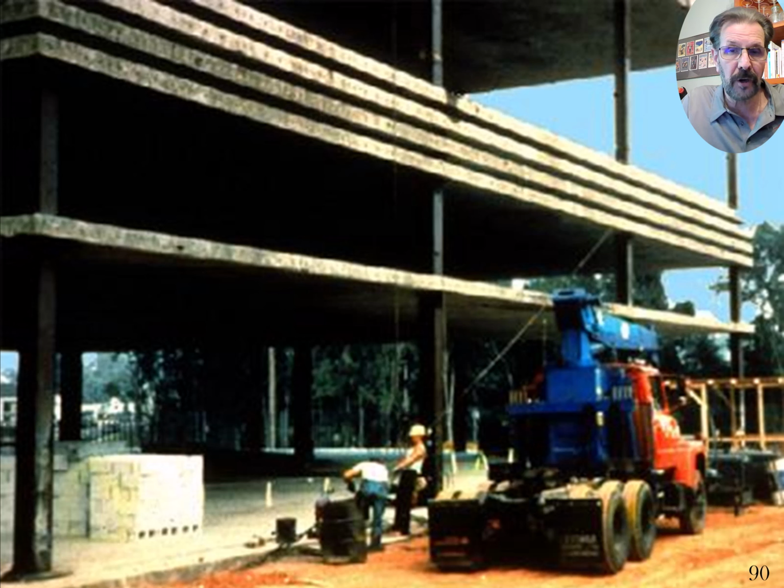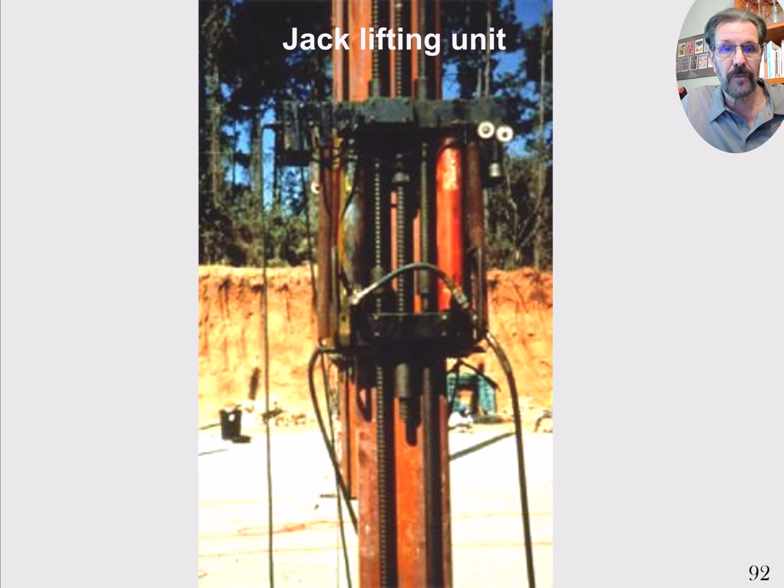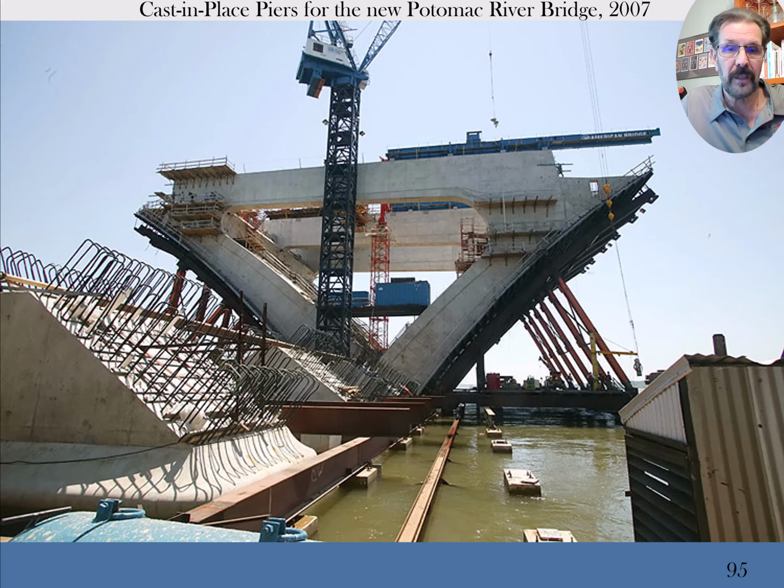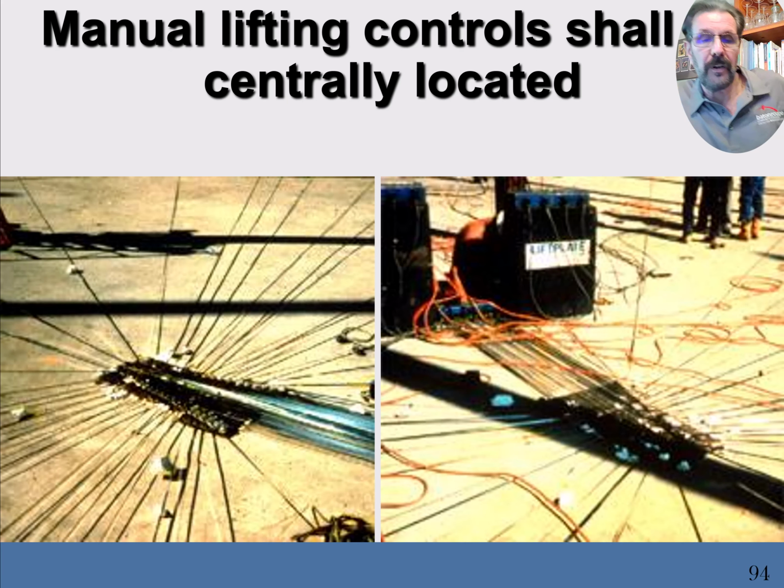So all they can do is hoist them up to the first floor and really heavily brace the ground floor, and then hoist them up some more and start bracing them again and rebracing as they go. As they go up and hoist them up, they eventually complete the building. So that's one system for lift slabs. I talked about the safety aspect of lift slabs in the safety class.